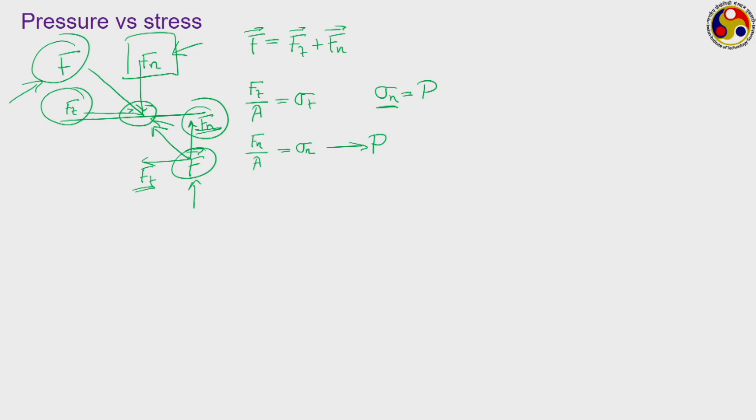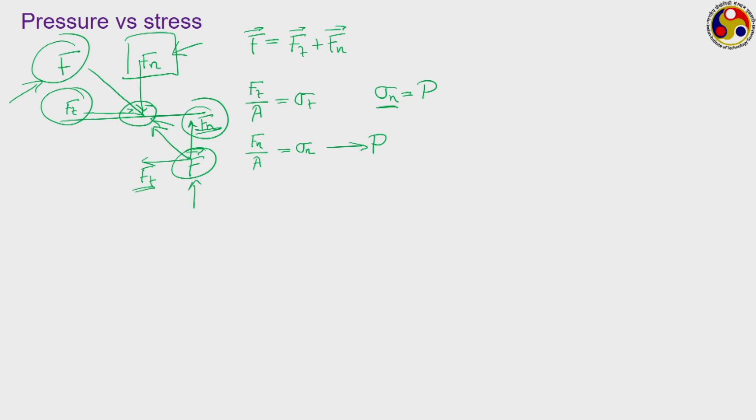So, though their magnitudes are the same, their senses are completely different. The stress corresponds to the internal forces, whereas pressure refers to the normal component of this externally imposed force. And another important factor is that the force corresponding to pressure will always point inward, that is, it is always compressive in nature, always pointing into the surface.